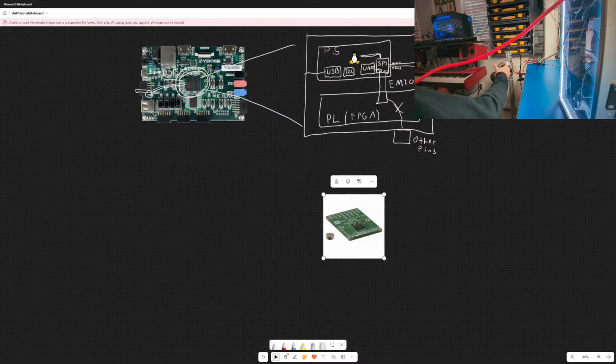And to accommodate for the jerkiness that I've seen when I control this with the RoboDog, you'll see it in previous videos, it's really jerky. It moves around like that, right? That's because it's going between two coils. It's jumping back and forth, and you can actually compensate for that. That's called anti-cogging, to compensate for the jumping back and forth. This is a characteristic of brushless DC motors.